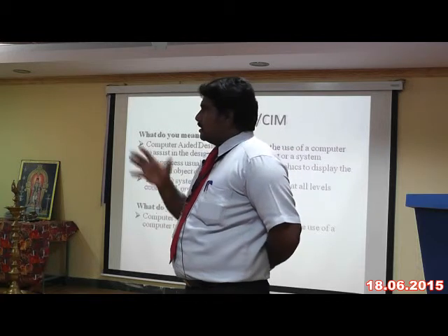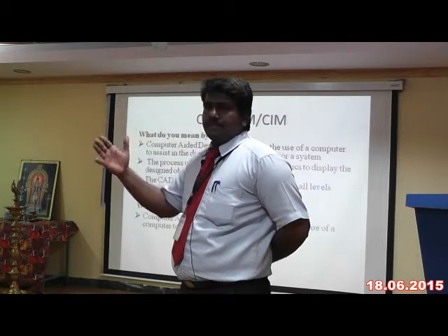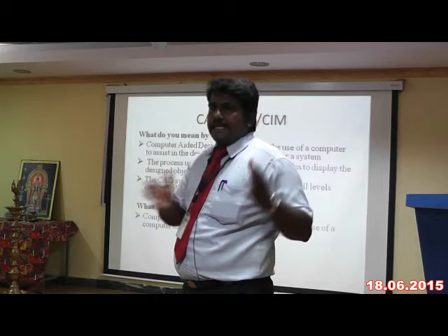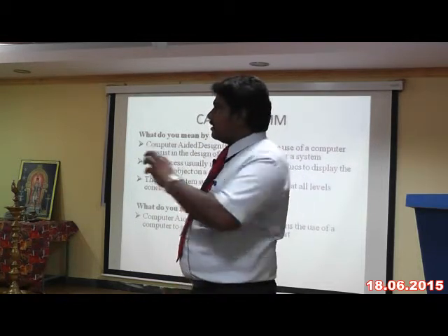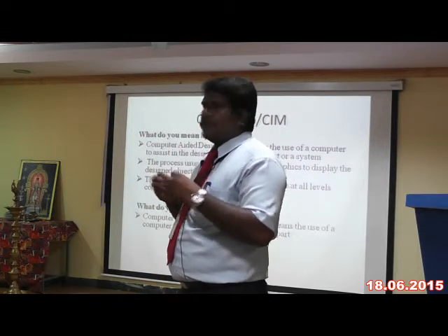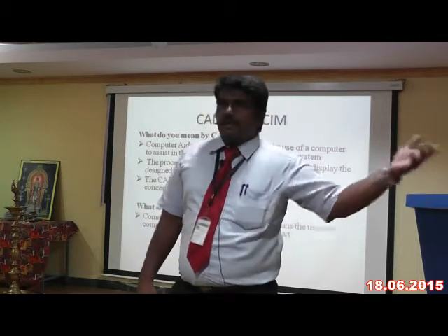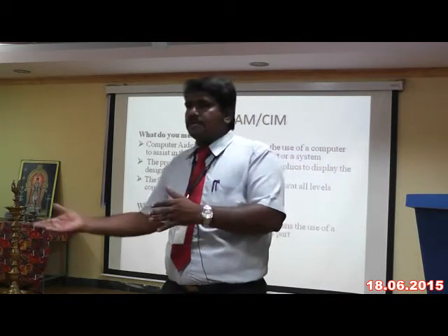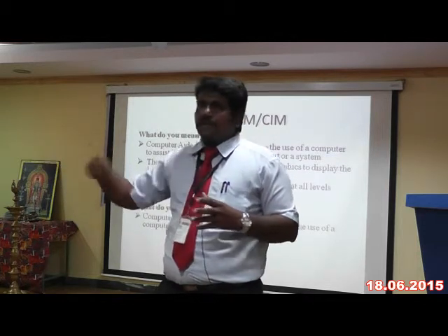Flow shop, in a sense, means all the machines are arranged in stages. Suppose we have some k number of stages, and at each stage there is only one machine. If you want to make a component, say a single rod, the first lathe will turn it and face it. At the next stage, the machine will do some taper turning, and at the next stage, some threading.